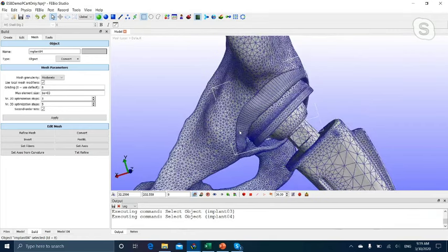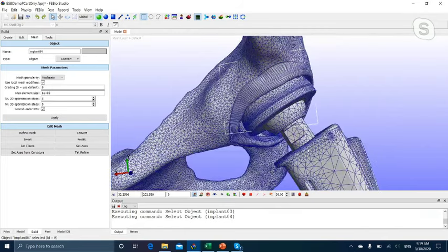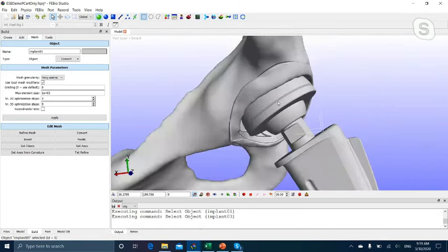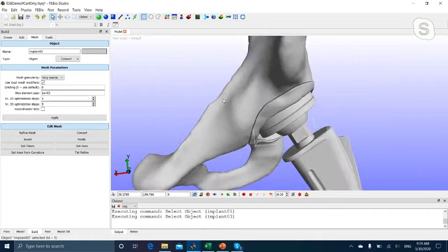Let's think about the physics. What I'm going to do is first move this implant up into the cartilage until it makes contact. The way I'm going to do that is by simply prescribing the displacement of that implant. Then I'm going to switch from a displacement control to a force control, because usually what people are interested in is applying a force to this implant, not a particular displacement. And then I'm also going to add a rotation to the implant as well. So let's get started on that.